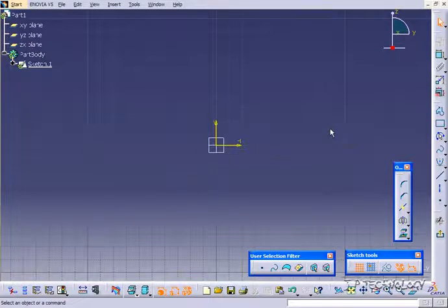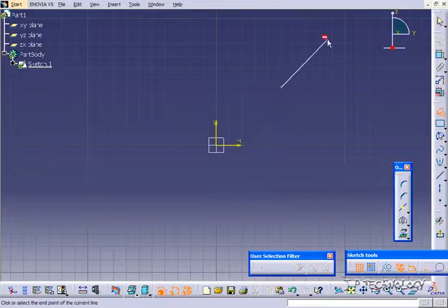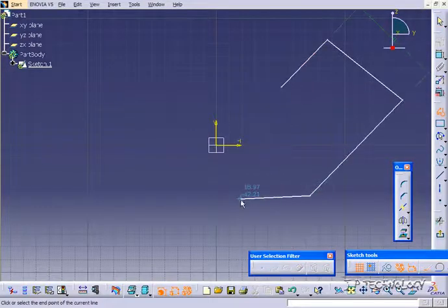What this is going to do is fix lines and points together so that they're constant within a sketch. So you're able to go around and dimension other components of the sketch without affecting the other sizes that have already been determined. To do this, let's start off by just sketching a profile. Just sketch a little profile out on the side, just something like this.